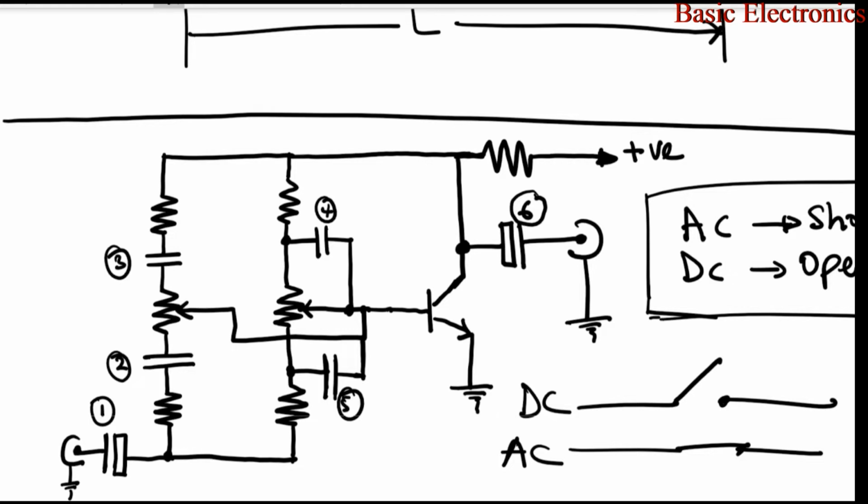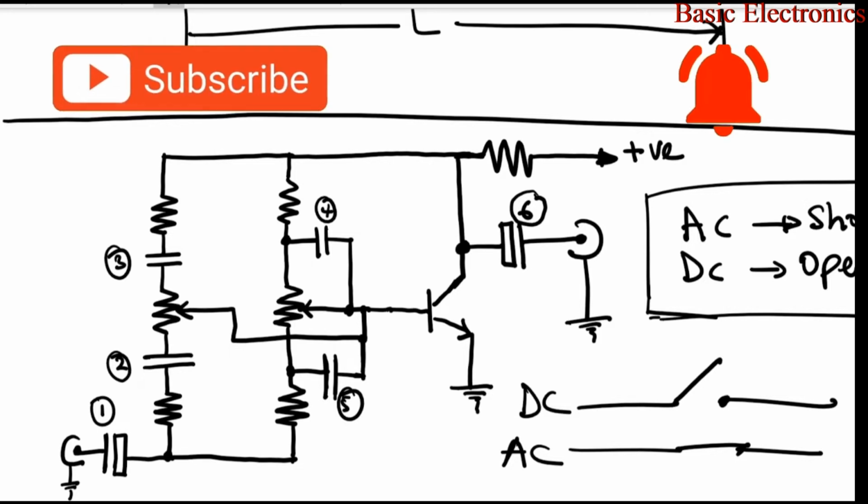Although I did mention that momentarily at power up, that's why I use capacitors as power up one shots. At the time of power up, there's a little jitter that can give a pseudo temporary feeling that the circuit was closed. But shortly after that, once the capacitor charges, it will open up, and that momentary closure is restored to open.